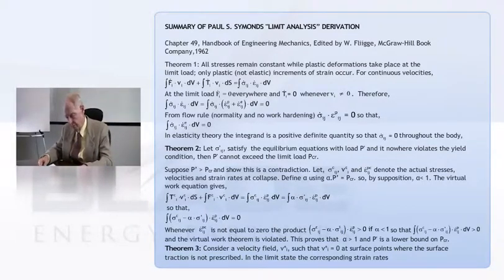Then on the second theorem, he writes the principle of virtual work again, and he does just exactly what Prager and Hodge do, really. But when he boils down his principle of virtual work, he ends up with, well, it looks like the last real live equation on that page, the integral of sigma ijc minus alpha times sigma ij prime.